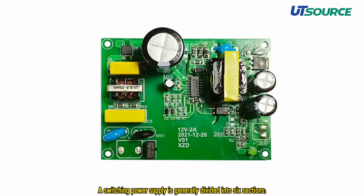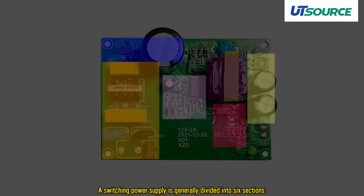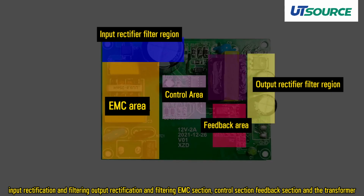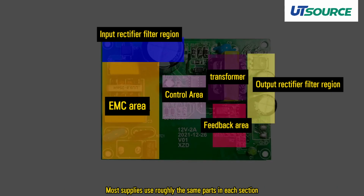A switching power supply is generally divided into 6 sections. Input rectification and filtering, output rectification and filtering, EMC section, control section, feedback section, and the transformer. Most supplies use roughly the same parts in each section.